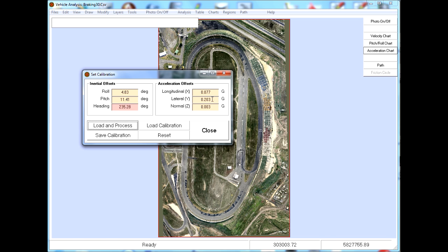This is a useful way to determine what the misalignment of the sensor box is if you don't have information from anywhere else. Again, like the configuration, you can load and save the files, and if a file of a specified name is found when the program starts, it will be read and those offsets automatically applied to the accelerometer data and the angles.